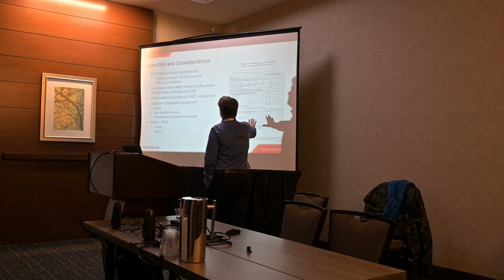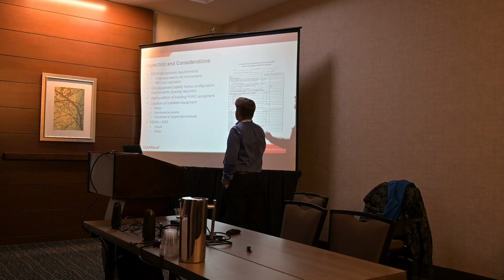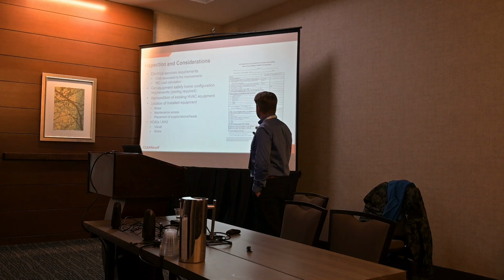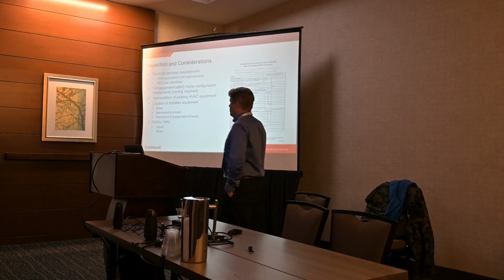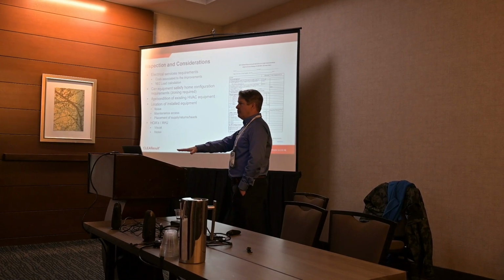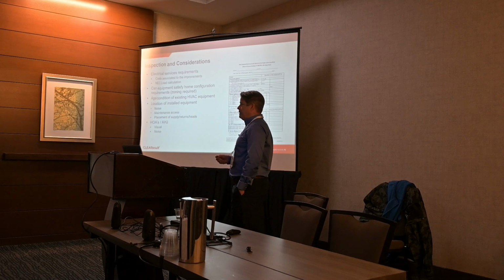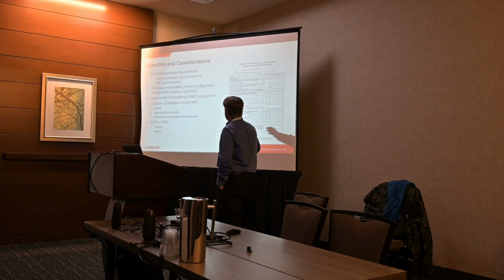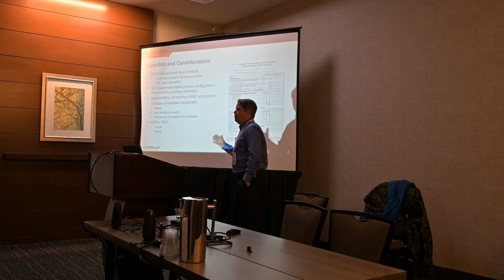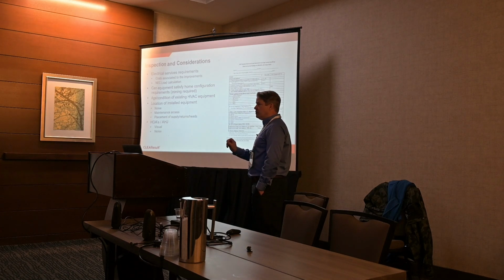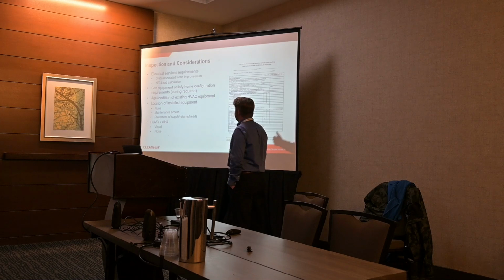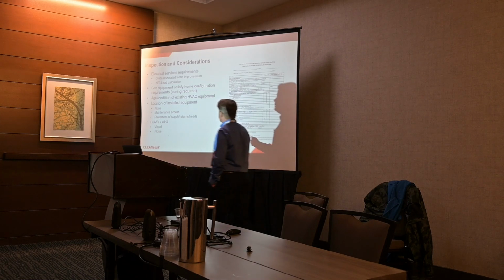We want to look at the house and the duct system and decide whether or not we could get better comfort by rezoning it some other way, okay? A lot of duct systems are just connected to an air handler, and it serves 1,000 or 1,200 square feet, something like that. And it might be that with these heat pumps now, with their smaller capacities, we can break that duct system up into smaller zones and serve it with a stage of capacity and very closely match a couple of rooms' loads to a stage of capacity, right? And if you can match the capacity very closely, you get much better efficiency and much better comfort, okay? So that's really what we're trying to do.